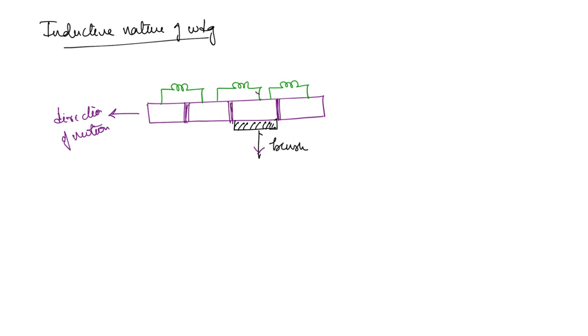So that means this coil will give some current, this coil will give some current, because there is symmetry. If you take this as 2 times some I, then each of the coils is giving the current I. Now you can see that in this coil the current is flowing from left to right, and in this coil the current is flowing from right to left. Now as the commutator moves in this direction, the brush will stay as it is. The brush is stationary, right? Commutator is the moving part.